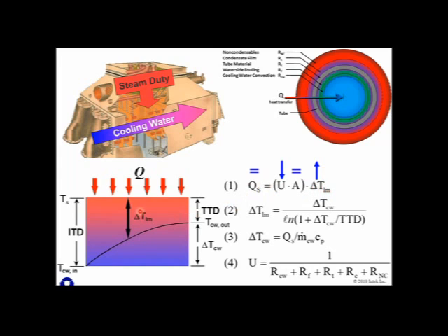And so in this delta TLM is the temperature of the steam, which is correlated by the steam tables to condenser pressure. In order to condense this duty with a lower heat transfer coefficient, you need a greater temperature difference between the steam and the cooling water. And so that is the reason why condenser pressure rises when you foul or when there's air binding or anything like that. You need a larger driving force to condense the same duty that's being delivered to the condenser.